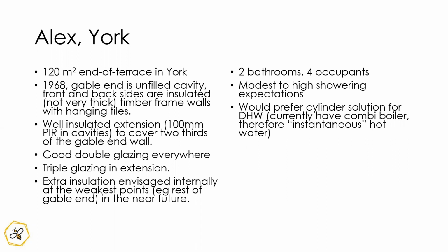Did you say anything about getting PV possible in the future? Because just sizing your heat pump according to your domestic hot water, it will run pretty inefficiently. I agree. And so thinking about using a diverter from the PV panels to heat up the hot water, I think would actually be a better way of doing it, right?